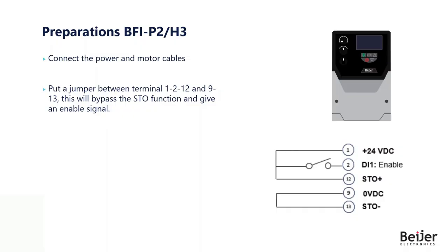Preparations of frequency inverter BFI-P2/H3. Connect the power and motor cables according to the installation instructions of the user's manual. The inverter has a safe torque-off input, and in this example we will bypass this input according to the following scheme.